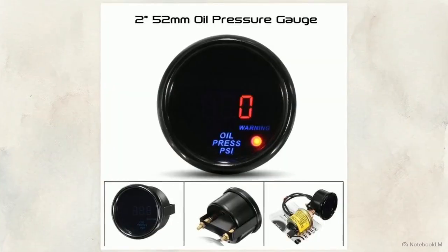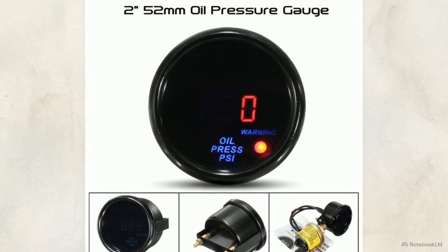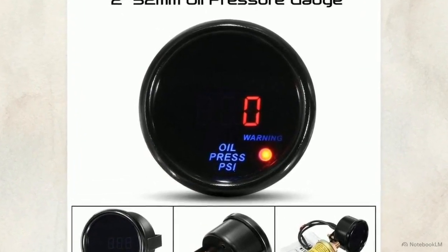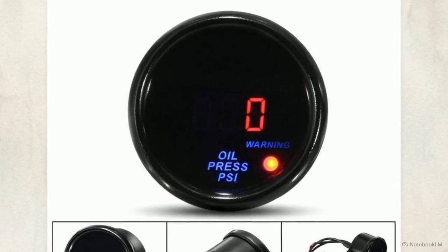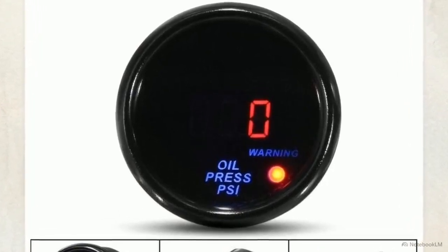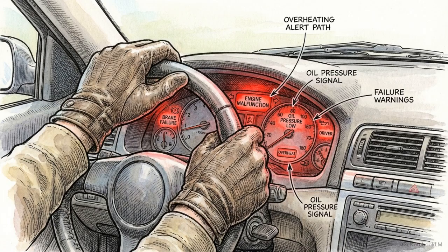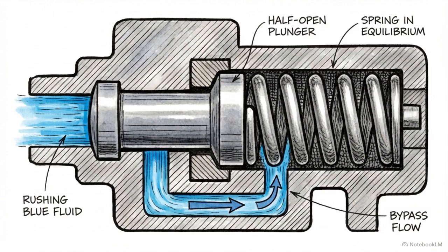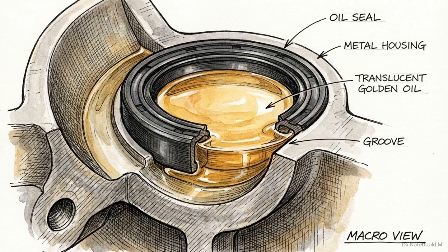In motorsports, monitoring this precise threshold is critical. A dedicated oil pressure gauge allows the driver to track the circuit in real time. Any unexpected surge or drop outside the normal range indicates a dangerous fault. The relief valve acts as the physical governor, perfectly balancing the mechanical output of the gear pump against the chemical viscosity of the oil to protect the engine's seals.